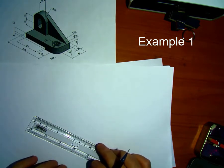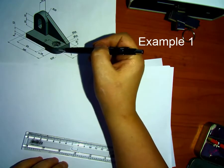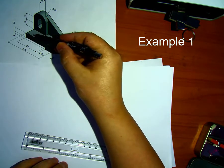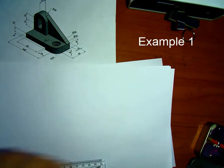First of all, what's the total length of the part? We have to look at this number. Okay, 100, the total length, which is from this edge to this edge. So I will start with my front view. My front view will be here in this area, then top, then right side view.